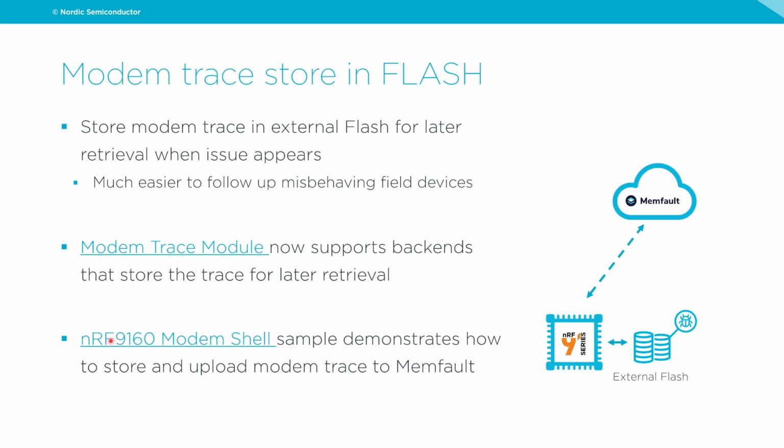And the nRF9160 modem shell sample now also demonstrates how you can store and then later upload the modem traces to Memfault. Once they're in Memfault, you can go to the Memfault platform, download the traces, and then use the Cellular Monitor application in nRF Connect for Desktop to convert them to Wireshark file format, and then use Wireshark to actually analyze the traces and look for any kind of misbehavior.